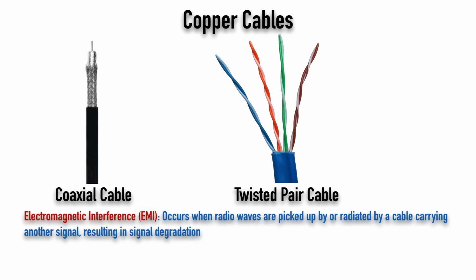With twisted pair cable, tightly twisting pairs of wires allows the wires to protect one another from EMI. What we're doing is twisting the wires where the length between the twists are less than 1/4 of the minimum wavelength being transmitted over that wire, and that way the wires are protecting one another from EMI.